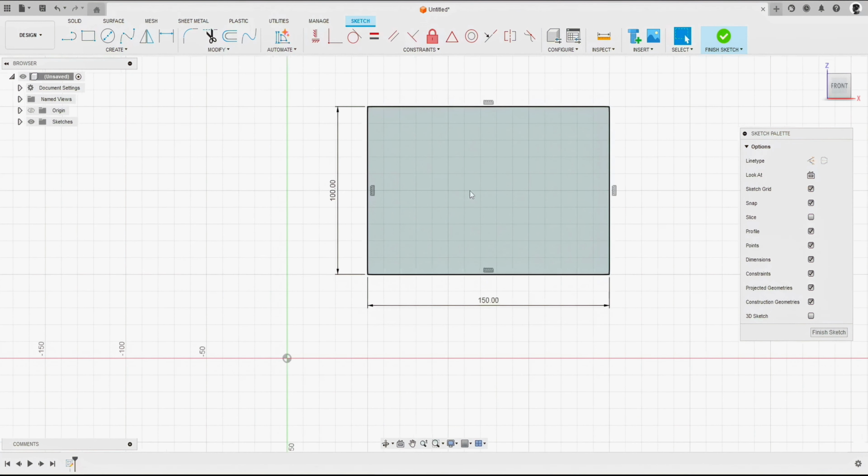And if we look at these dimensions, 20 here, and then we've got fx20. Now fx is a function, okay, so it's referring to something. We hover the mouse over there, it's referring to this dimension here, which is d8. If we double click here, it just says it's referring to d8. So if I go ahead and change dimension d8, and I enter there, let's go for 15. We can then see that we've changed the horizontal by 15, and then the function has read off of that dimension at that both 15, and that remains as an equal distance chamfer.